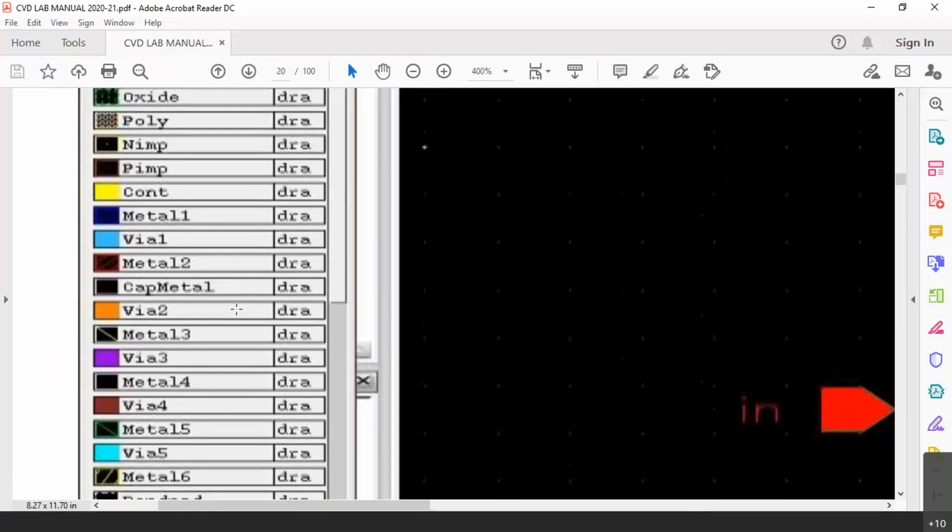Whereas for gate connections, polysilicon is sufficient. For source and drain connections, they should have the least resistance, because polysilicon also contains some amount of resistance. For gate connection, poly is alright, because there is no gate current at all for the MOSFETs. But between source and drain there is a current flow, for which we cannot use polysilicon. We will have to use a more conductive material.